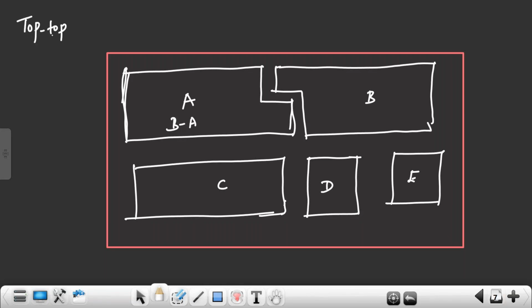So the chip top team will first partition this entire design into different blocks, and each and every block is given to each and every engineer to do physical design. After doing physical design, the chip top will integrate all these blocks, form the chip, extract the GDS for this, and send it to the foundry. So this is the full chip. The full chip is formed by what? Integration of different blocks.